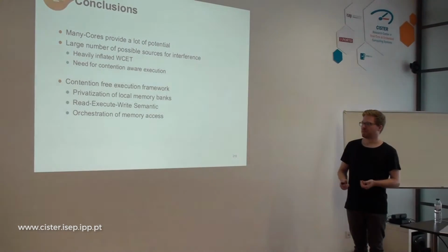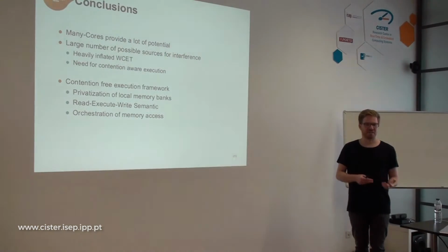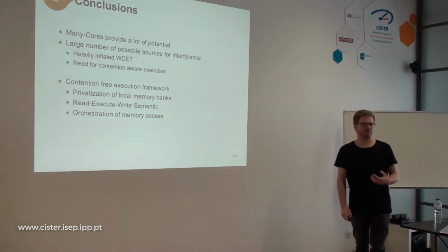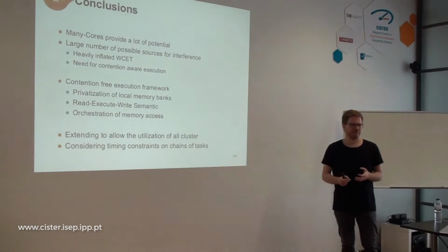This led us to our contention-free execution framework, which is built on three key points: privatization of local memory banks, the read, execute, write semantic, and then we orchestrate the whole memory access using our time-triggered schedule. For future work, of course, for now we just utilize one cluster.